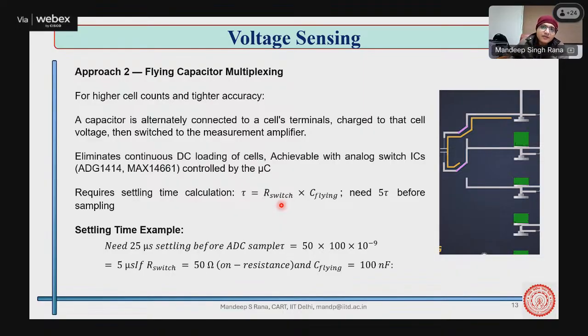So to do that, we put a sort of RC element which falls into these two bands. One is it can sample fast enough for my data to be transferred, and another is it should not act very fast, like in the megahertz sort of range, to avoid all the unnecessary noise.